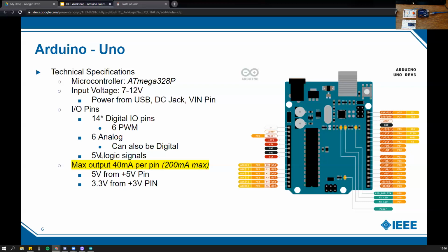As you can see, this gets a little bit more technical, might be a little bit beyond the scope of this, but there's a range in between where it's indeterminate, and that's what you call floating, and that's something that we're going to try to avoid in our circuit right here, and I'll talk about that a little bit later. But basically, you don't want to be in that range between 2 to 3 volts, because at that point, the Arduino, it's a digital device, so it doesn't know, is it a 0 or is it a 1? So it's kind of just guessing, and you get a lot of noise in there.